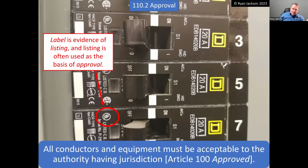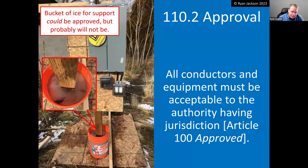Now, circuit breakers, believe it or not, up until the 2023 NEC, circuit breakers did not have to be a listed product. And now they do, so I can look at the UL mark there and I can say, okay, it is listed and it's probably suitable, right? But if that wasn't a listed product, how would I as an inspector know that that thing is going to behave safely? How would I know when it's going to trip, if it's going to trip at 20 amps or 2000 amps or maybe not at all, right? So all things must be acceptable to the authority having jurisdiction, and listing goes a long way to help that process. But of course, the code can't talk about everything, right?